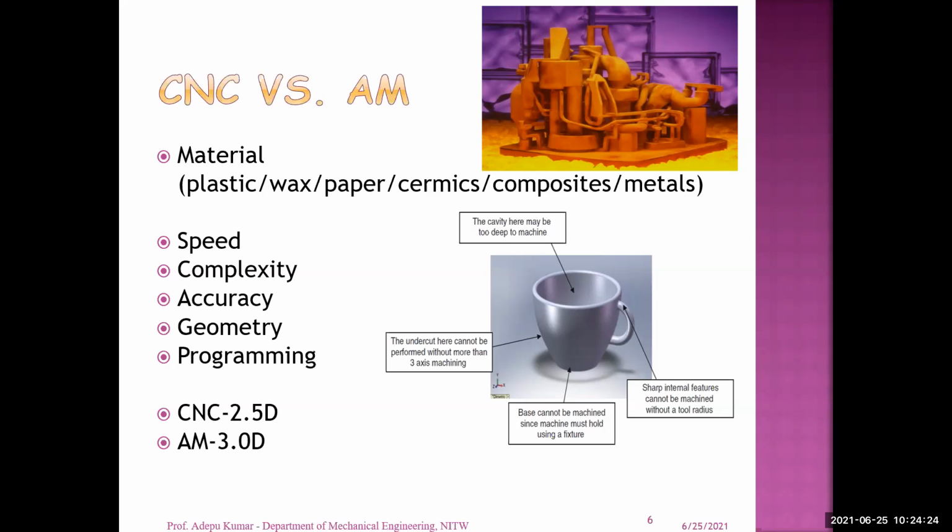Okay. Once you select a CNC machine, your work material, ceramic, is a very hard material, so the cutting material should have much higher hardness than ceramic. That is one important criterion. You can select, let us say, diamond as the cutting tool material. Now you can go for machining. Which type of machine is required to generate this component? Definitely you can go for a 6-axis vertical milling machine. I can provide all the accessories to generate this component. Then after fixing the component, you machine it using the 6-axis vertical milling machine.